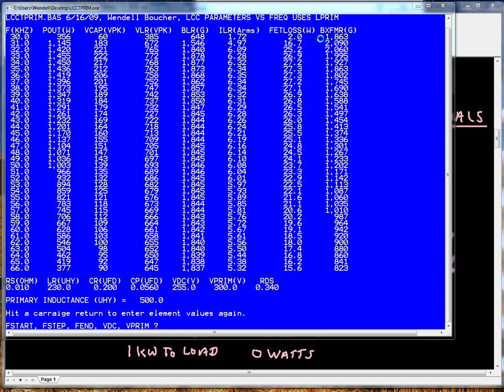And this is the flux density seen at the primary of the transformer. So if that transformer had 1 centimeter of area and 100 turns on the primary, we'd be operating at 1200 Gauss. So obviously we're going to change, in both cases, the area and turns to suit our needs accurately.